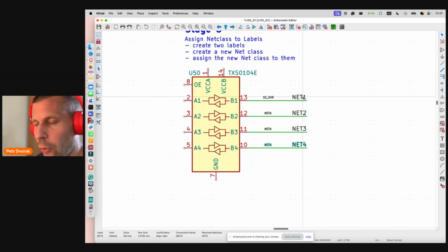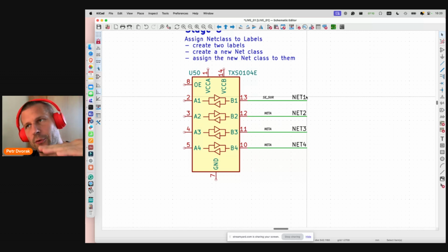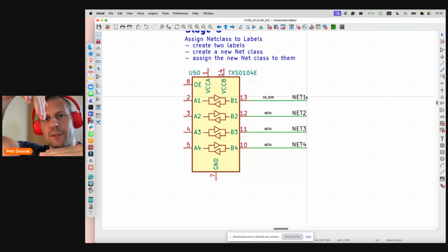Plus, when I talked about the horizontal mirror, there is a vertical mirror as well. It's naturally Y, and then you can easily mirror vertically not only the symbol but the labels as well. And it's practical on occasions when you need to mirror a connector. For instance, you are designing the schematics for a carrier board, and then you design schematics for a board to be plugged from above or from the bottom. And now you need to be careful with the orientation of the connector.